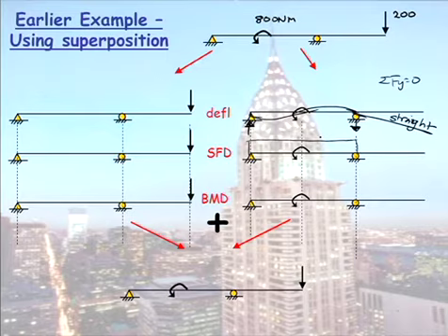So my bending moment diagram now. What's it look like? Can you imagine? We know it's 0 here, and this time we know it's 0 all the way along here, don't we? There's no action in there. The beam is straight, moment is proportional to curvature, there's no moment here. So we have a 0 moment up till here.